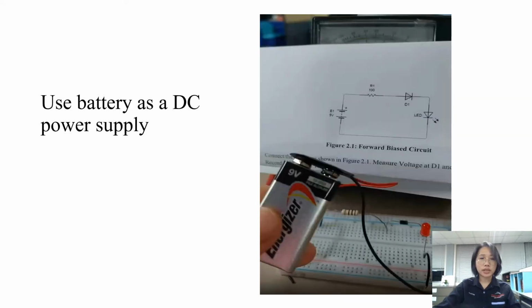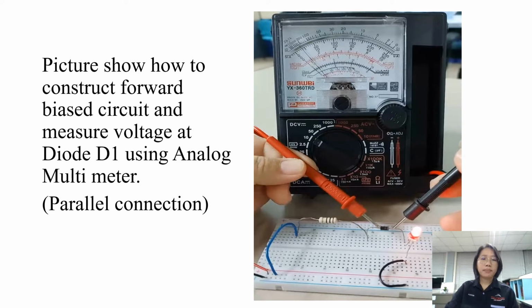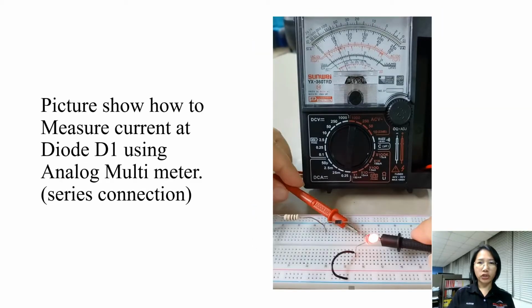The picture shows that battery is used as a DC power supply. The picture shows how to construct forward bias circuit and measure voltage at diode D1 using analog multimeter. The analog multimeter is connected in parallel connection with D1. The picture shows how to measure current at diode D1 using analog multimeter. The analog multimeter connected series with the diode D1.